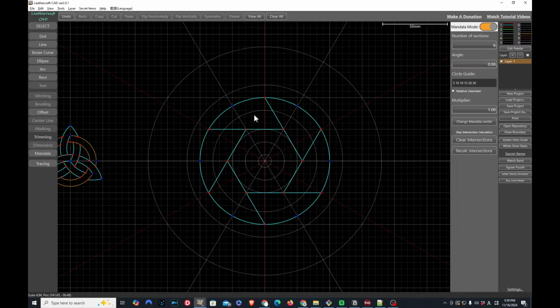So making, oh, sorry, this is trimming. Let me undo this one. Okay, I should have pressed this one, offset. So it will create a 3mm offset, and maybe 3mm is too much. So let me change it to 2mm. Okay, now it's 2mm. So let me do this. Oh, by the way, I forgot to change the color. So Control Z again, undo, and change the color before doing it, and then offset.